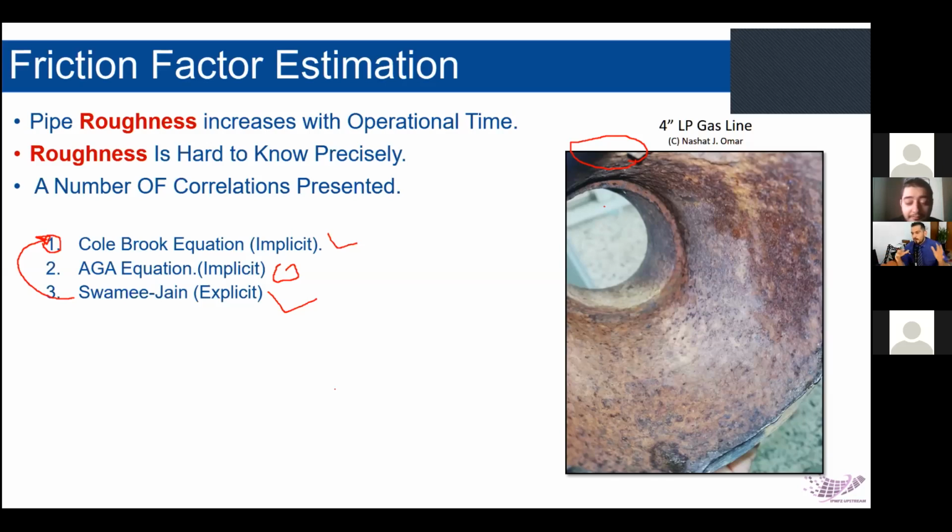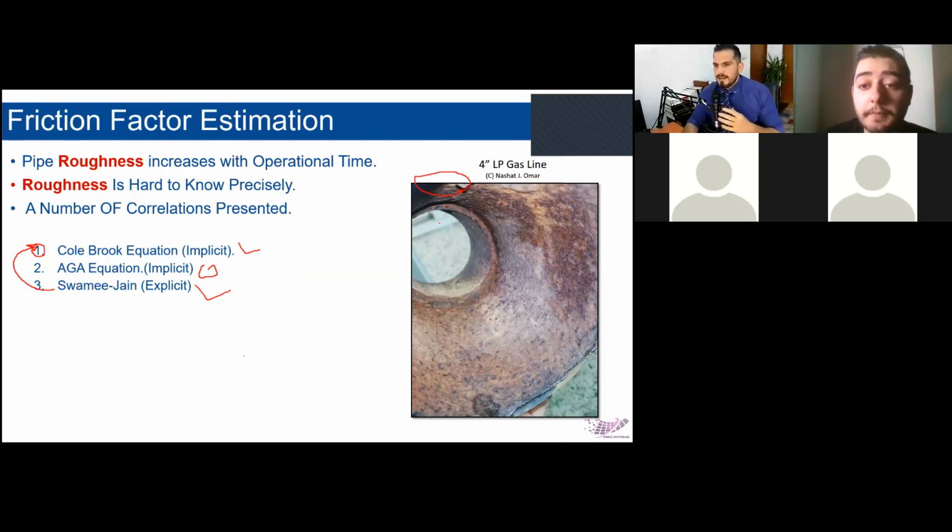So what do you do inside the reservoir so it can give you the deliverability for your reservoir? You will input the VLP curves. Am I correct? Okay, so let's assume you have a specific reservoir model and you want to produce from that reservoir. You insert all of these types of wells and configurations. However, how Eclipse or CMG calculates the pressure drop inside the well itself, it uses something called the vertical lift curves, correct? Okay, go ahead.